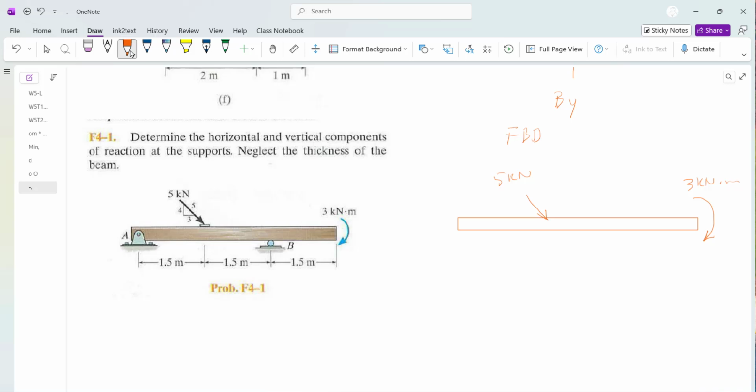And if you open up A, like usual, because it's the hinge support, we are going to deal with hinge support and roller support in many problems. Not that all supports are of that type, but these are very common ones. So AX, AY. And then at B, we do have a vertical reaction only because this is a roller contact.